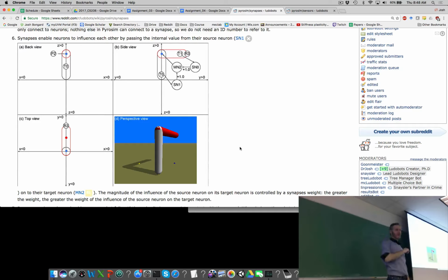Depending on how fast it does that. If it goes slow enough, then it might stay at that angle until it falls. But if it goes fast enough, it could pick up its original leg and spread back out. Absolutely, right? So it matters now how fast and strong the motor is. In later assignments, you're going to be able to tune the strength and the speed of the motors. We're not there yet. At the moment, the motor is relatively slow and weak. So it is going to flex in a little bit. You'll see it actually start to pull inward faster than it would if it was just falling passively. But it's not going to get to 40 degrees from one time step to the next, right? The motor's not that fast. It's going to move in a little bit.